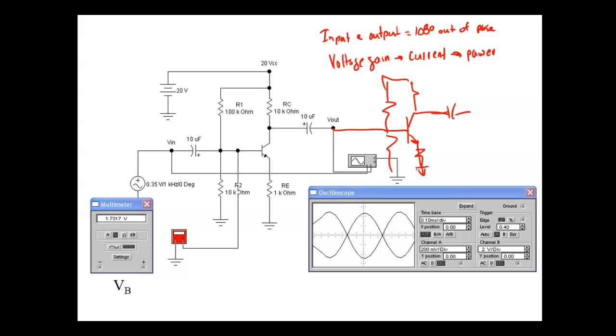So if I'm coming over here from a sensor, like a microphone, I don't know what the impedance of this is. Can I measure the impedance of this with an ohmmeter? Huh? But it's an inductor, because it's a bunch of coils of wire.